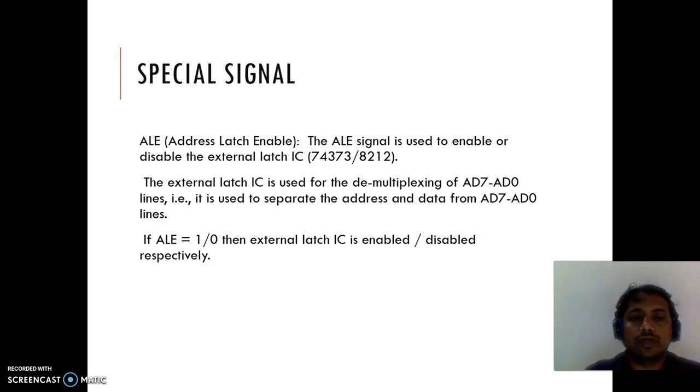All these are connected to octal latches. Usually we will have octal latches. Octal latches means 8 latches put together, so 8 plus 8, 16 latches. These latches hold the address information once you use this address latch signal. This is a special signal.